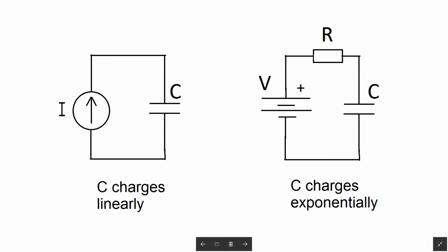In this video we will talk about charging a capacitor. So let me give you the answer right away. If you charge a capacitor with a current source, the capacitor charges linearly. If you charge a capacitor with a voltage source, the capacitor charges exponentially.